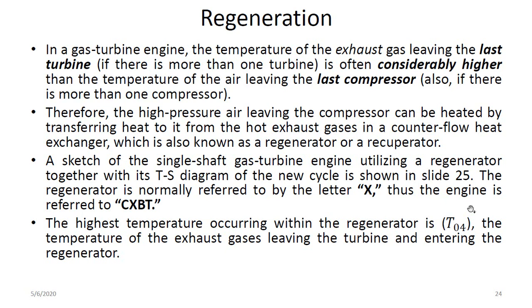For an aircraft engine, this is a good thing because the higher the temperature, the higher the exhaust speed, because the temperature is related to the exhaust velocity. So the higher the exhaust temperature, the higher the exhaust speed, and that translates into a higher thrust. But for an industrial gas turbine, because this is a stationary module that is maybe used to generate electricity, you don't want the exhaust gas to leave at a higher temperature because that would be energy wasted.